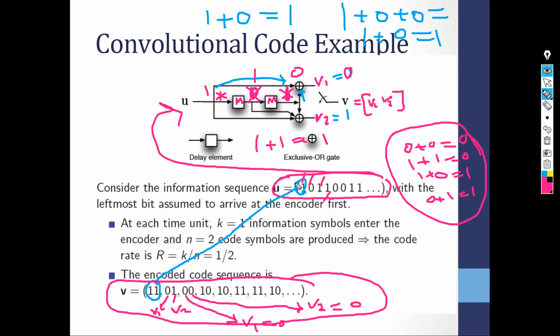At the end, if I give you an information sequence U, containing binary bits, zeros and ones, and tell you to encode this information sequence to a code word V that can represent my message, adding some parity bits that can protect my data from the noisy channel, you should be able to find the V that you need to transmit instead of U. So you don't transmit U, the message signal, directly. Instead, you are transmitting V. Clear?